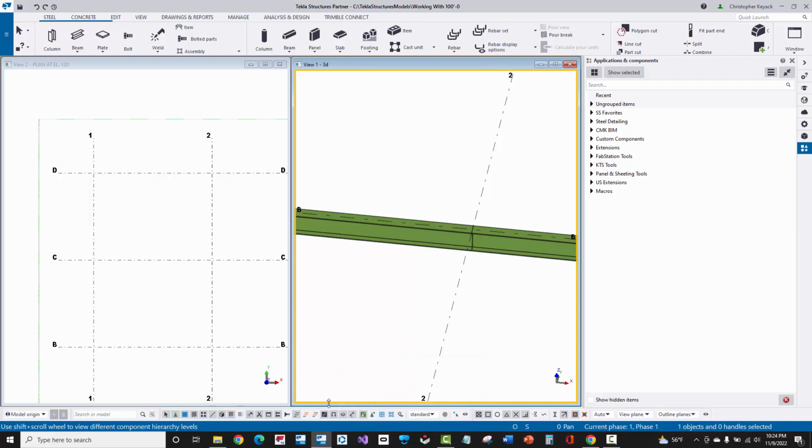Now, this last set of selection tools basically allows me to control what type of objects I'm choosing. If I only want to select grids, I can deselect everything by clicking the select all button at the left. You'll see that it allows me to just select parts. I can deselect that and just select grids.